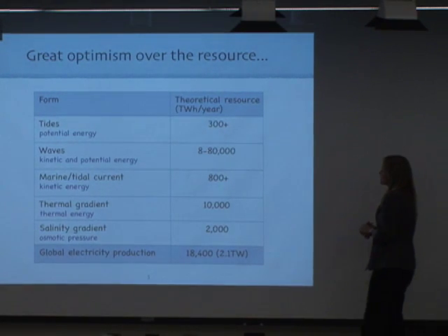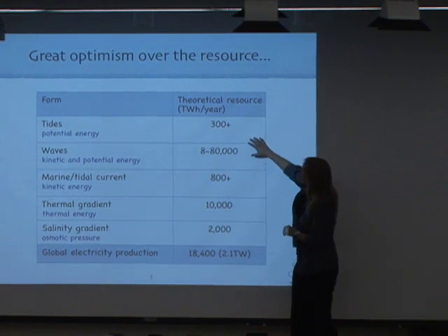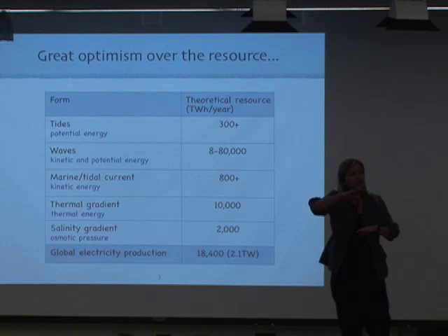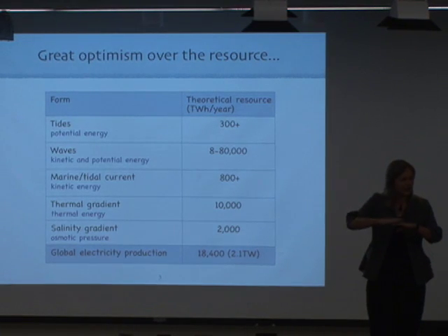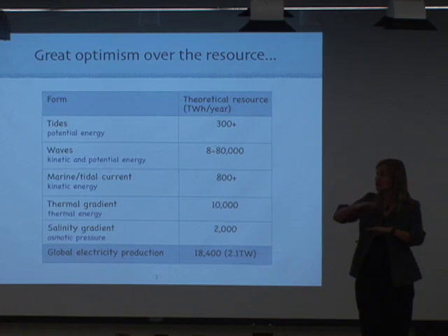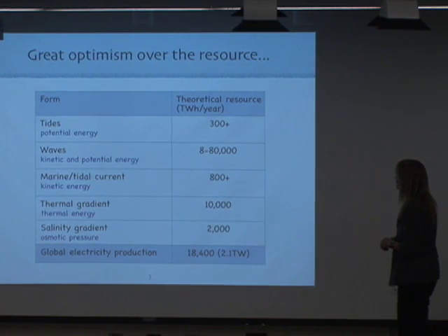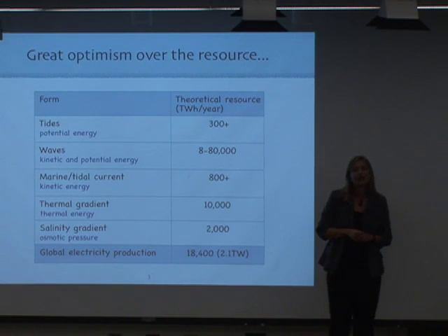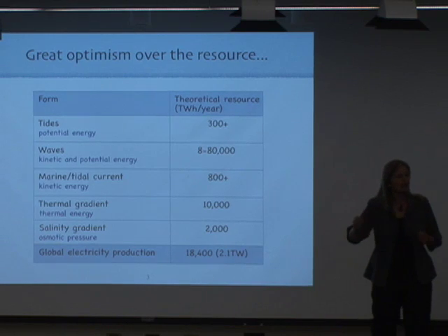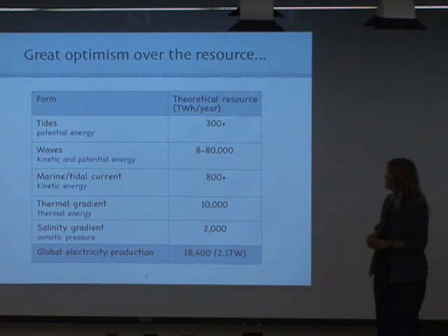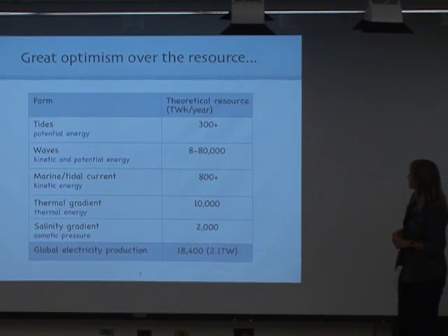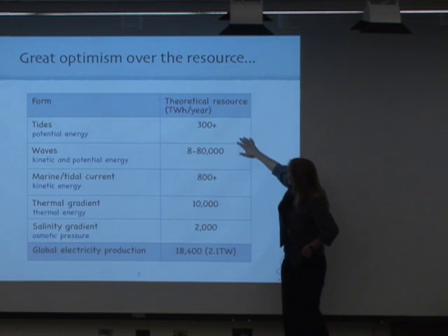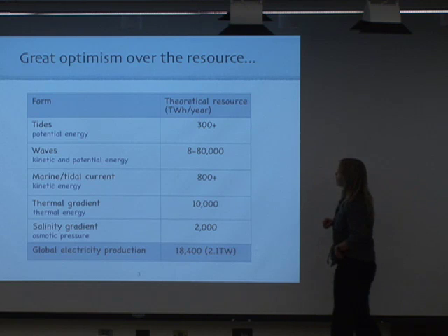There are two ways you can extract energy from the tides, which we'll discover. One is potential energy, where you're looking at the elevation of a mass of water because of tides, and you're tapping into that potential energy that is created every tidal cycle. But you can also look at the kinetic energy associated with tidal currents that are flowing because of these elevation changes in various parts of the globe.